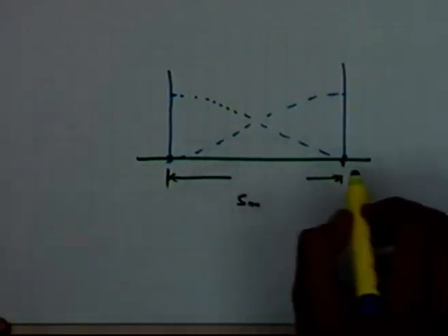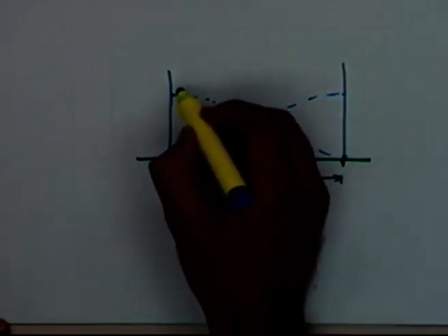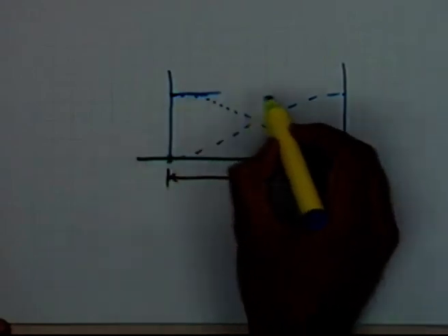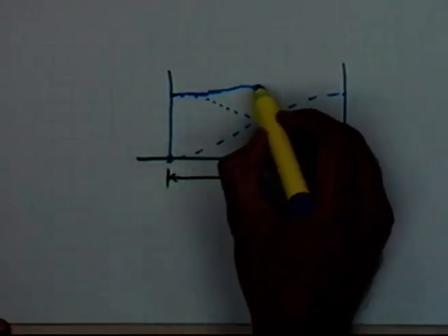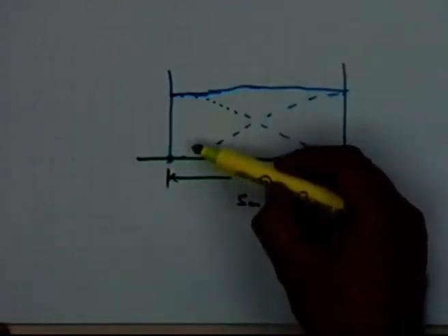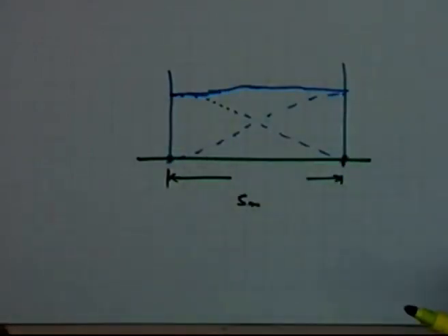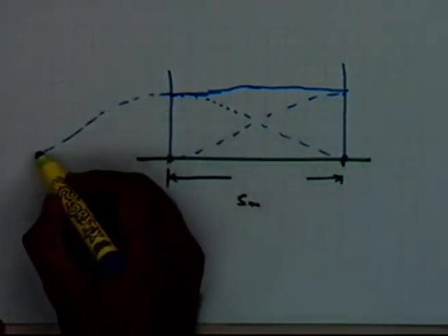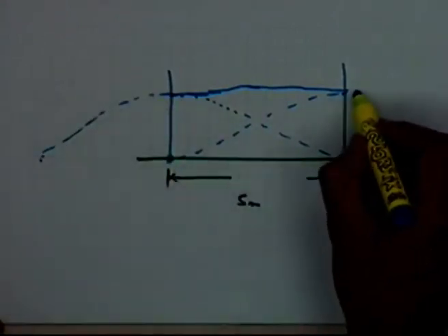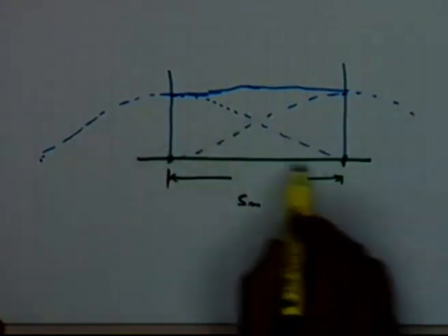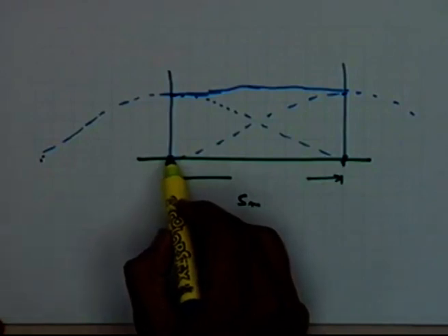Then the overall application will be the combination of these two, which gives some total depth, the net effect of these two individual patterns. This is half the portion, the other half will be on this side. Similarly, this will have the other area of influence. This total distribution pattern is for a specific individual sprinkler head.